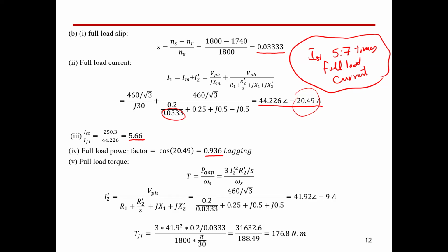Otherwise, if the machine reaches a certain temperature, which may melt the machine windings or affect the core, this would burn the motor. So we have to evacuate the motor heat from the machine in order to allow it to work safely. So we have one of the classes, class S1, which works 24/7, which means we care about the steady state, not the transient, in terms of the power factor.